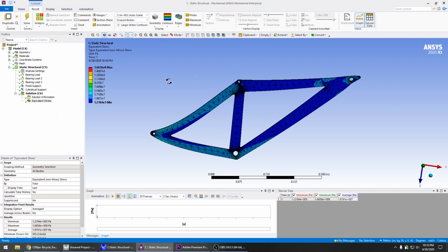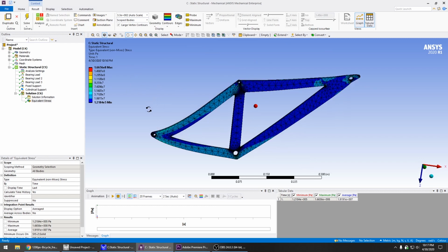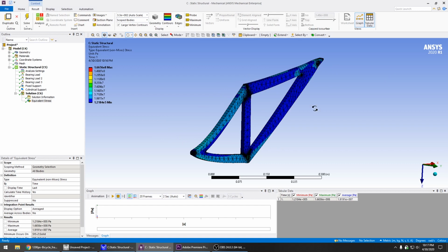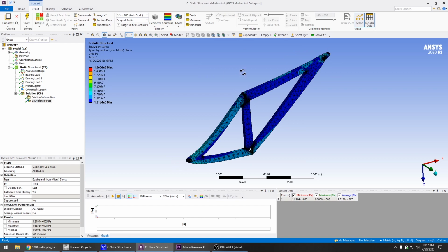And then we check our factor of safety based on this number here. You get to choose, based on your judgment as an engineer, what you deem an acceptable factor of safety. In this case, I don't know if the guy who's riding it is going to weigh 250 pounds or if he's going to be 100 pounds. So I need to design in enough safety factor that this will survive in the case where the larger person rides it, but is also acceptably lightweight for the smaller rider.